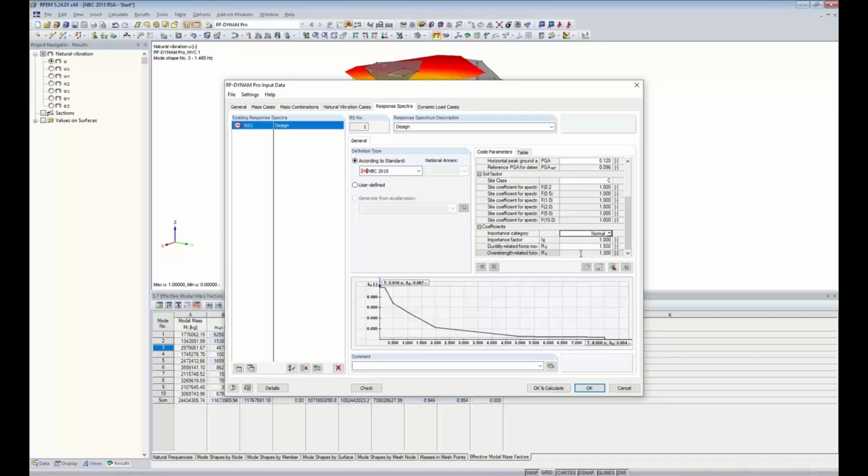And for today, we have a concrete structure. We're assuming conventional construction, and the seismic force resisting system will be set to shear wall. So for example, today, our RD value will be 1.5 and our RO will be 1.3, which is actually the default settings here. Now, these factors are considered for the response spectrum when we have the type of spectrum set here to design. So again, I'll get into this later, but you will want to input this information, which is considered here.